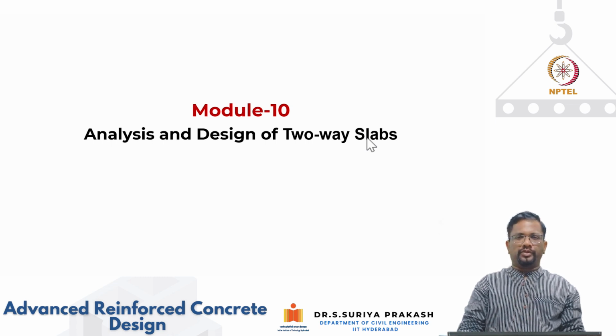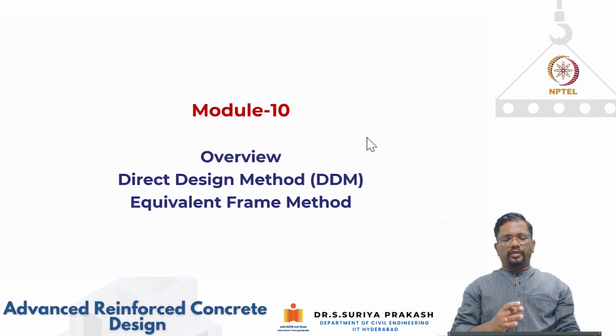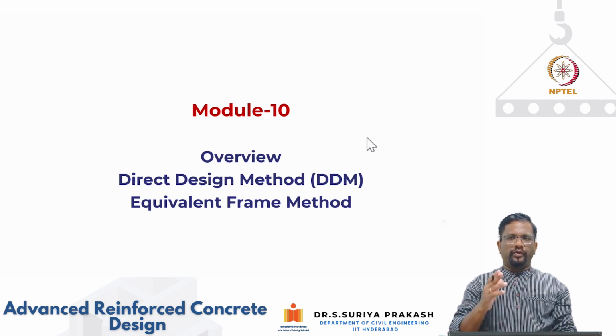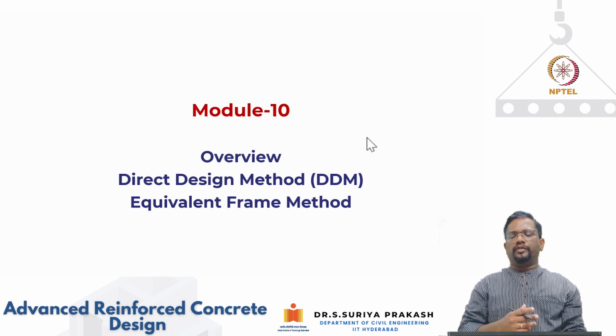So, two-way slabs is a very important topic. We'll cover that in this module 10. In this module, we are going to talk about an overview of different types of slabs. There are two popular methods that are commonly used for design of these slabs, at least for hand calculations, which are the direct design method and the equivalent frame method. These methods are usually used to check the results that you're getting from your finite element analysis.